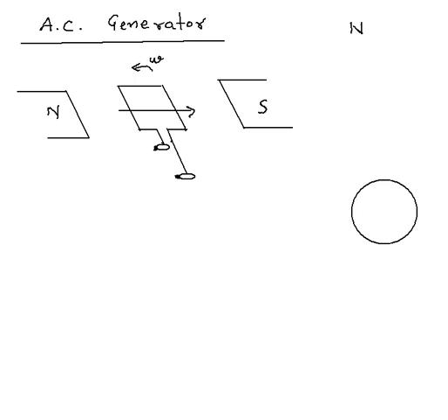So you can think of it like this: this is a zoomed version of a ring. If something is rotating like this, there is something here which is always in physical contact with this ring. This thing is always in physical contact with the ring, and it is the carbon brush. So one here and one here. The carbon brush is not rotating. It is rubbing at this point of contact.